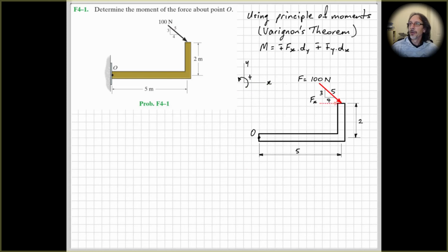All right, so our horizontal component is this one down here, Fx. And if we complete the little right-angled triangle here and use Pythagoras and trigonometry, from our ratio of triangles here, we get, using the ratio, 4/5 times 100 gives us the length of this side. Okay, so that's why we've got 4/5 times 100 here. If you're not sure about this, go to the trouble of using trigonometry to work out these angles here. You can use tan of 3/4, or cos of 4/5, or sine of 3/5, inverse of those, to find the angle.